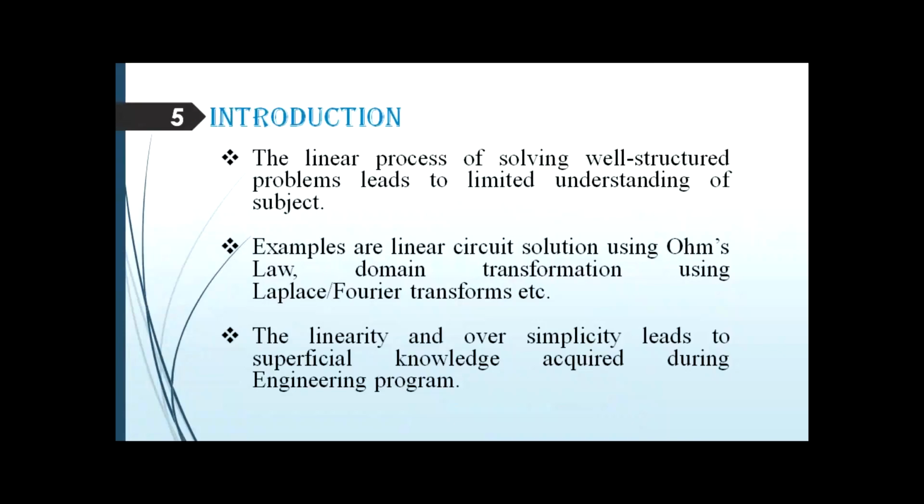If I ask you to compute the convolution of two signals, you can easily say, okay, integration from minus infinity to plus infinity of x of tau multiplied by h of t minus tau d tau, and so on and so forth. It's quite an easy and simple procedure. It doesn't involve complexity within it.